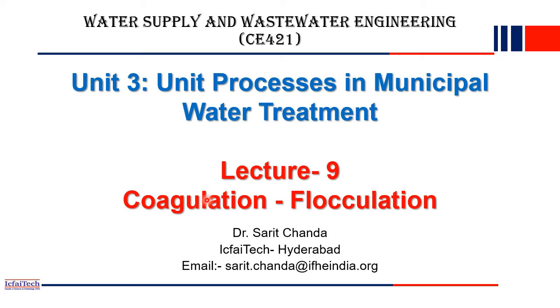Now in the last few lectures we are discussing how to remove the fine suspended particles present in the water. As we have seen, small suspended particles will still be present in the water. Those types of particles won't settle down to the bottom in primary sedimentation. Why? Because the mass of the particle is very less and the particle is very fine, so it exhibits Brownian motion in the water, and it will always roam in the water.